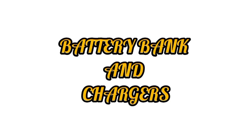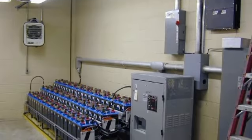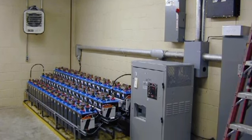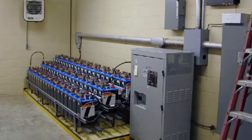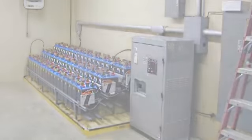Battery bank and chargers. Provides uninterrupted power for protection and control systems. Backup typically lasts 2 to 6 hours depending on load, usually 220 volts DC or 110 volts DC systems.